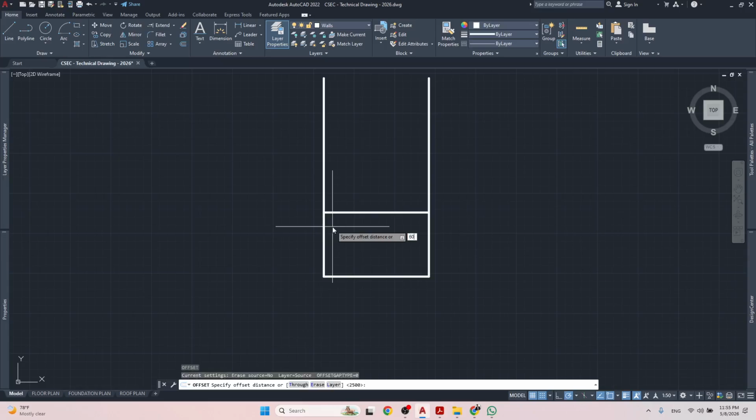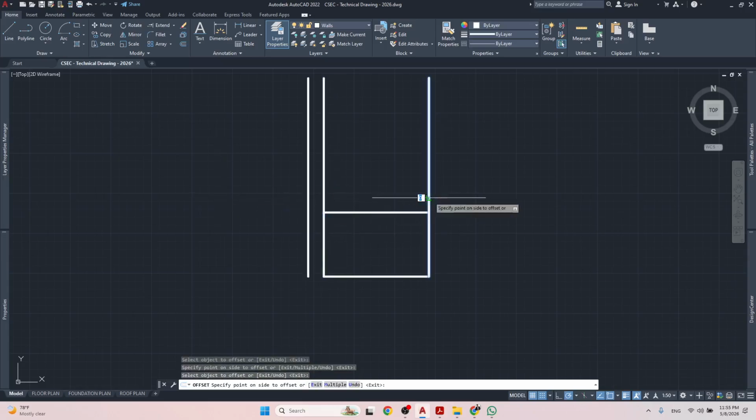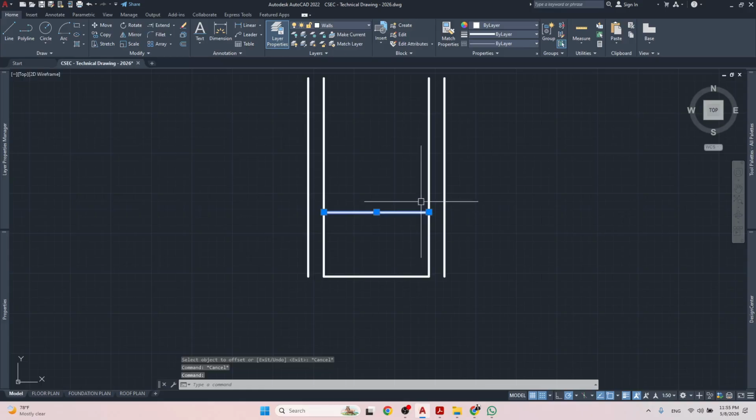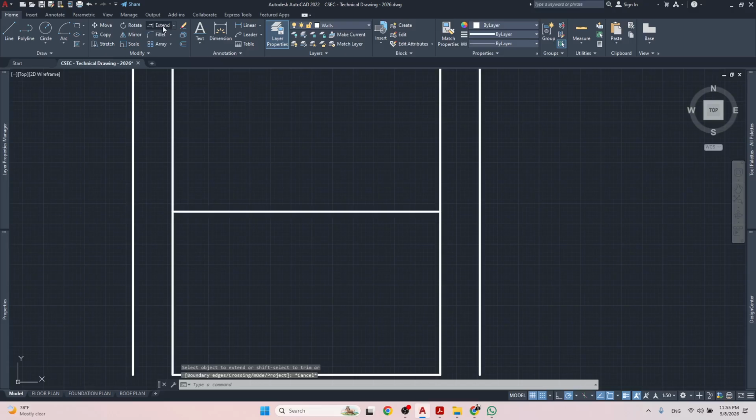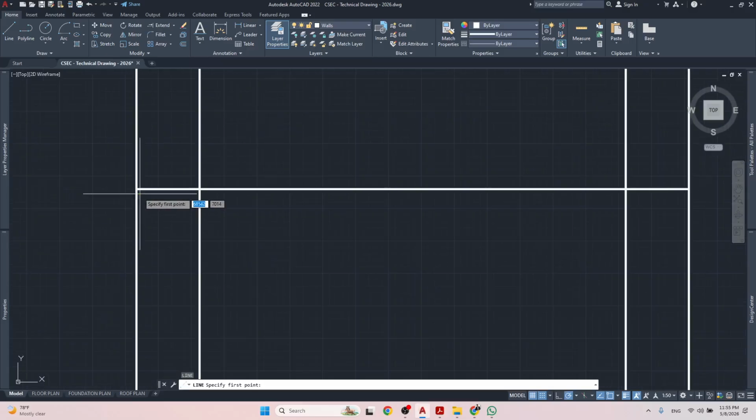So I'm going to offset 600 millimeters on that side, and that is where the eave is going to meet. So if I extend the bottom of the eave out to meet the overhang, that is where they will stop. All right. So let me just draw the eave completely. Let me turn on my auto mode so my lines remain straight.